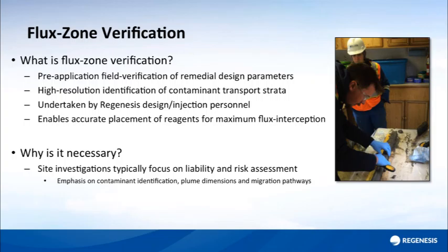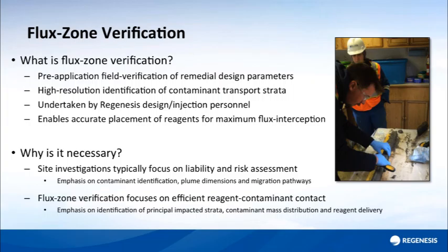So the emphasis is on the principal impacted strata, on the contaminant mass distribution within these strata, and on the parameters that we need to know for reagent delivery. So there may be water injection tests, there may be hydraulic profiling, and there'll be various forms of sorting of cores, as you can see.